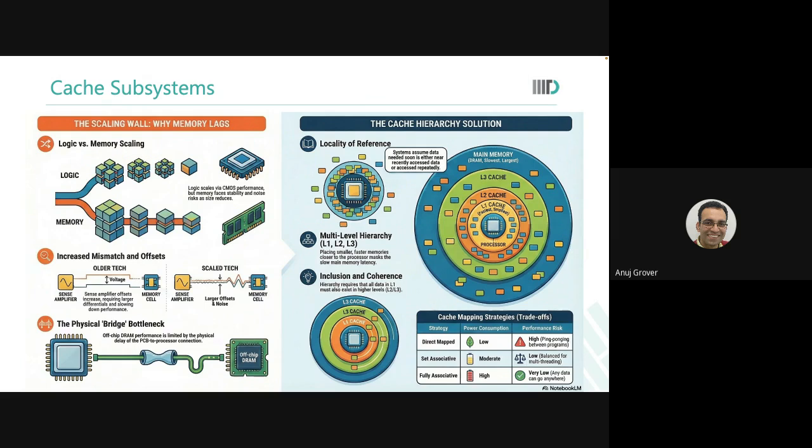So to reduce the spatial conflicts, we should not just abruptly increase the block size, but instead we can increase the cache size. But if you increase the cache size only, what happens? The intrinsic performance of the memory degrades. Because a 1K cross 32 memory is much faster than a 2K cross 32 memory by virtue of smaller RC there. Are you able to see this?